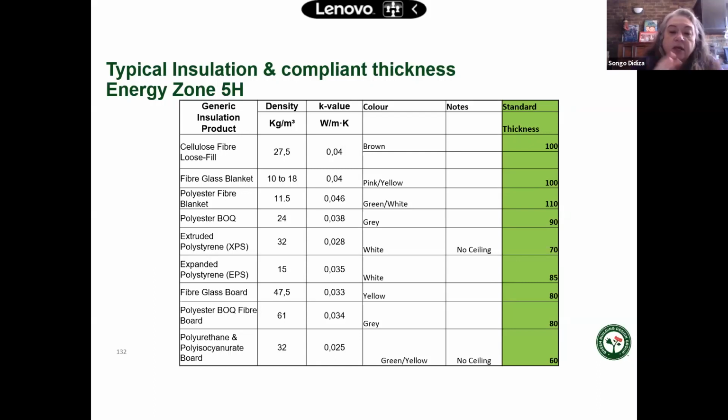They trap pentane or different chemicals, and these, what we call blowing agents, have a very, very low thermal conductivity, which means they've got a good thermal resistance. And that's how you'll see, with thickness, the boards are probably more effective at a lower thickness because it's not air, it's a chemical that they've trapped. And it's not a dangerous chemical, so don't stress about it. Well, some of them.